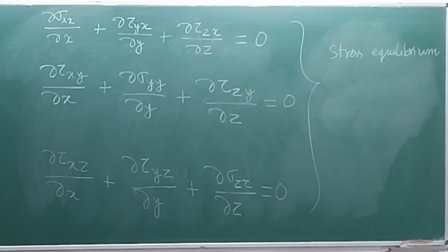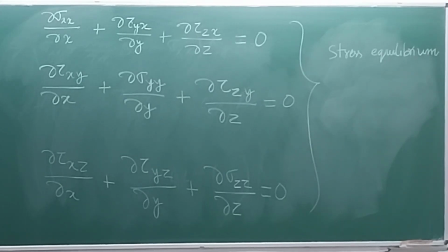Suppose you have a parallel plate channel and you have the fluid which is static there. There is no pressure acting on the fluid. Now, if you slide the top wall, will the fluid not move? But there is no body force. Suppose you take this entire device, this parallel plate channel, again into deep space. No body force, nothing. Gravity is minuscule. Even there, if you slide the top wall, the fluid will start to move.